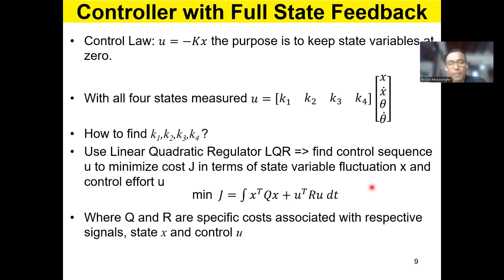All right. And we have to specify Q and R. Q means how costly the errors are, right? In the 4 states, if they're not 0, how significant is that and how costly is that, in other words, right? And the R, we specify R on our own, saying that my control signals are expensive or cheap, right? If I use petrol, for example, for this controller, and if petrol is very cheap, this R is a very small value. It's not significant. But if I use petrol, which is very expensive, then R is a higher value, like that.